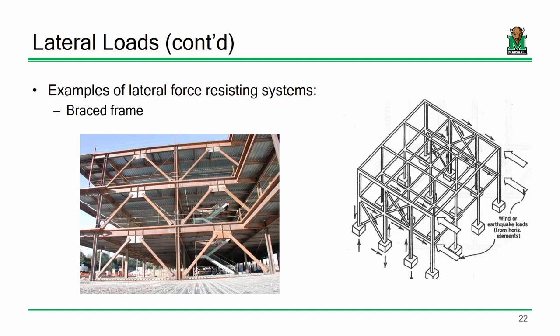So for instance, the two primary lateral systems that we use in steel buildings are either braced frames or moment frames. A braced frame is taking literally diagonal bracing elements, almost as if we're treating this entire bay as a big truss, and this is what holds the building up under some lateral effect like a wind or an earthquake event. We don't place those braces everywhere, just in very specific locations. Where we place them is largely a function of two things. We try and get the most structural efficiency that we can out of those braces, but there's also the architect. Architects like nice open windows, and more often than not, they don't like these big diagonal braces covering their windows. So sometimes we've got to be a little crafty where we put them.